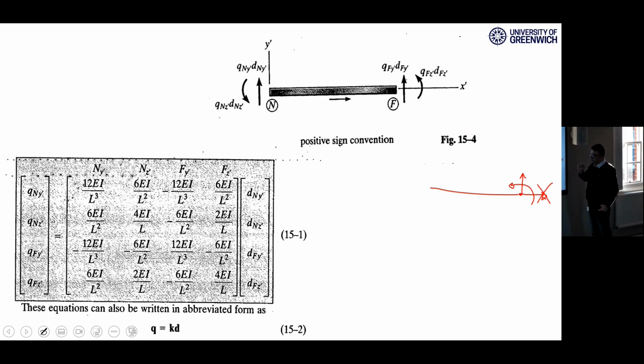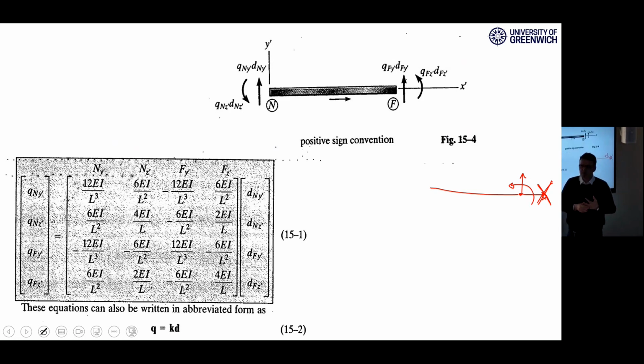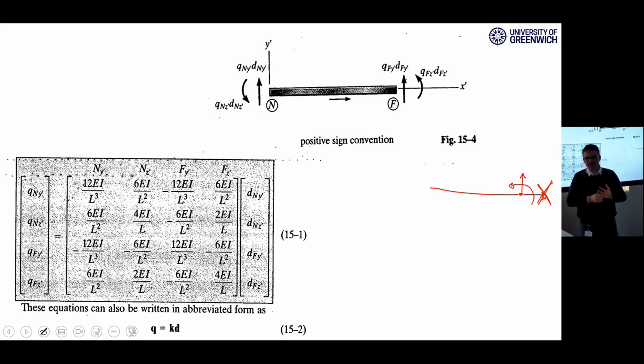We neglect this one because we don't have too much axial force. In frames, we can do it differently, but here we just neglect axial deformations because we know that we don't have too much axial force. And really, they are negligible. Axial deformations are negligible. Why? Do you remember any place in this module where we talked about the fact that axial deformations are negligible?